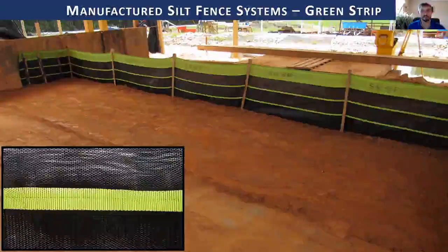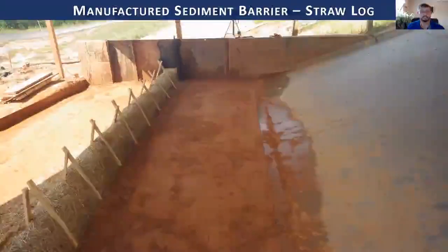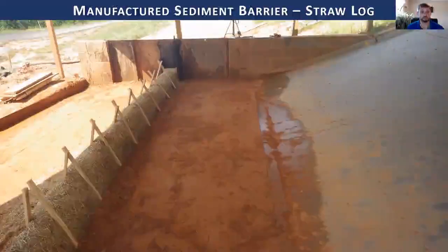So this is another type of practice that we evaluated. We actually looked at several different types of manufactured sediment barriers, such as a straw log. So we looked at these different types of straw logs installed in various manners. So we did straw logs sitting on the ground surface. We did straw logs entrenched 2 inches into the ground, as well as straw logs sitting on top of a geotextile-like barrier that helped prevent undermining during testing.